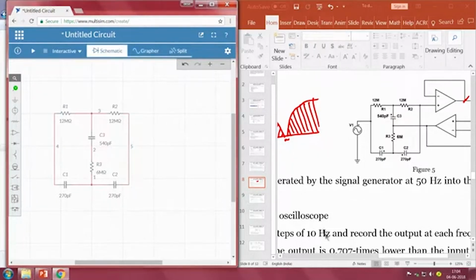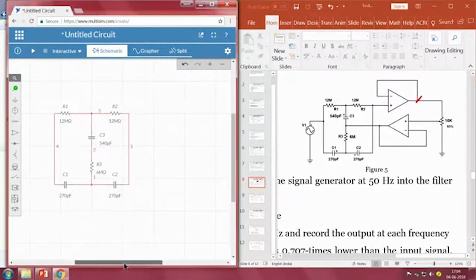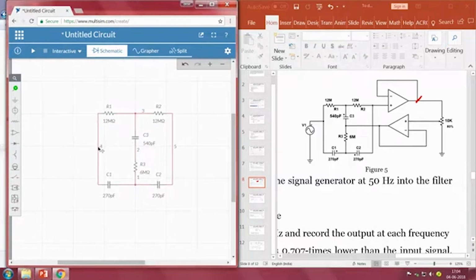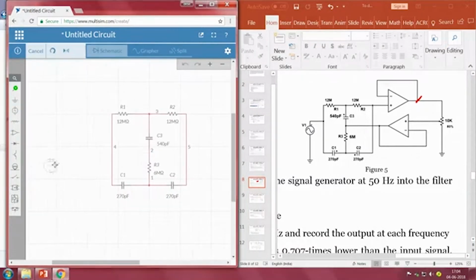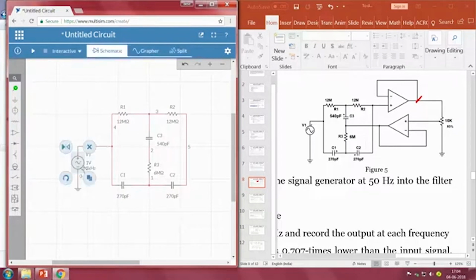Right. So, which looks similar to that of our circuit if you observe here. Now, the input should be connected at this point. So, what I will do is take an AC voltage, connect it here, and the other terminal should be connected to the ground. So, we are thinking to take a resistance value, the voltage source with an amplitude of 1 volt peak value. So, peak to peak we can select it as 2 volts too, right. So, relatively it is easy to understand our output voltage.